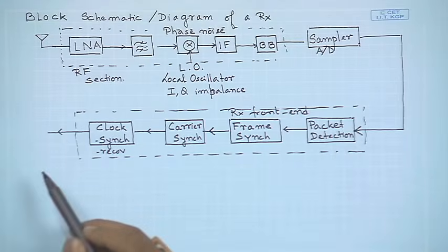Now while it is awake, it is not a good idea to make the entire receiver operation on. It can simply keep the detection part on, which would set up an alert that yes, a packet is being received. So once that alert comes, the rest of the receiver can wake up, right? So this was going to reduce the energy consumption or the power consumption of the system. So there are different methodologies. So that's why we can have a packet detection in the beginning.